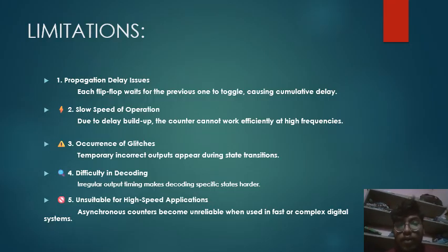Each flip-flop waits for the previous one to toggle, causing cumulative delay. Slow speed of operation: due to the propagation delay build-up, the counter cannot work efficiently at high frequencies. That means at high clock frequencies, the asynchronous counter does not work effectively.